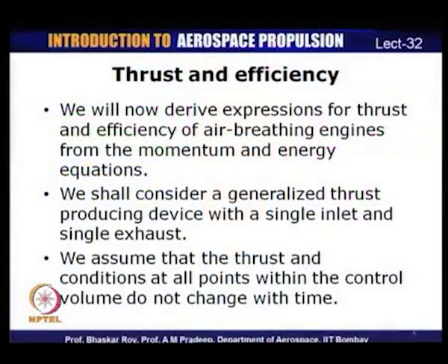So, what we will do first is derive expressions for thrust and efficiency, which basically come from the momentum and energy equations. We will consider a generalized thrust producing device with a single inlet and single exhaust. And there are engines, as we will see in the next lecture, which have multiple inlets and multiple exhausts, basically those which concern turbofan engines and so on, or in fact even turboprops. So, these are engines which have multiple inlets and multiple outlets.